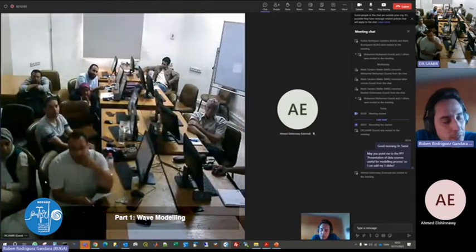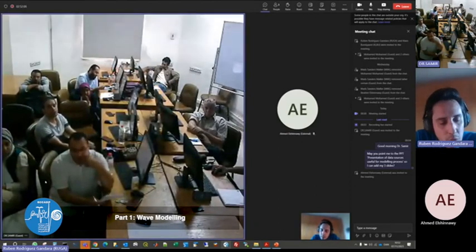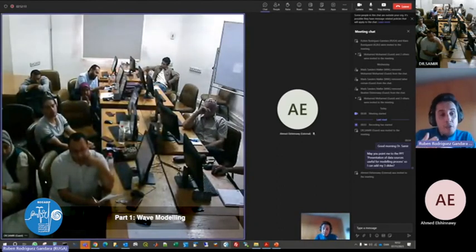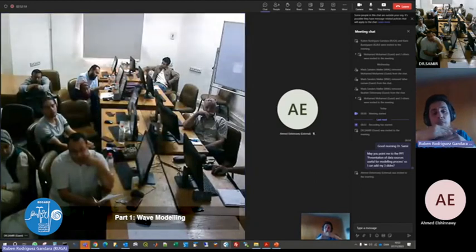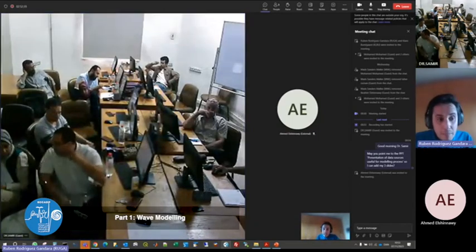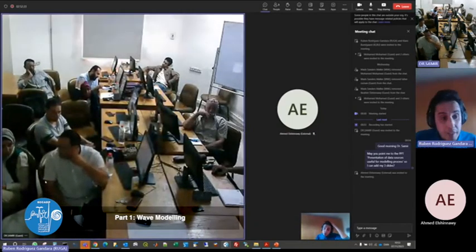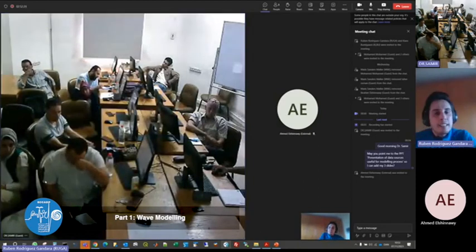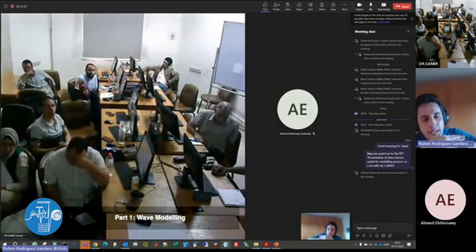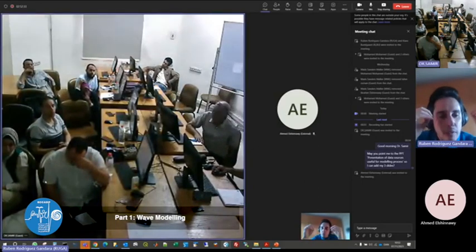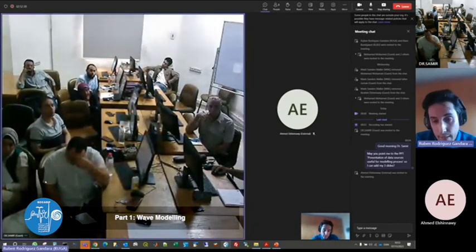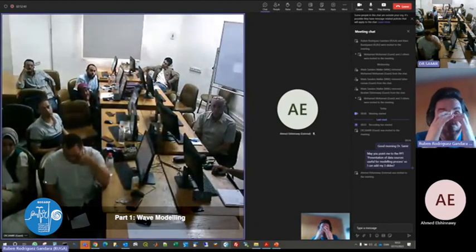So that's the thing. Whenever you're going to design a harbor, or an LNG terminal, where you have structures and they cause diffraction, and you are planning to moor a vessel on the lee side of the breakwater in order for it to have calm and not be affected by the waves, you need a diffraction model. Mike SW can give you the information about what is happening in front of the breakwater, but what is happening behind is not going to be accurate. You need a model that properly models diffraction, which is Mike Boussinesq or the Mild-Slope equation program.